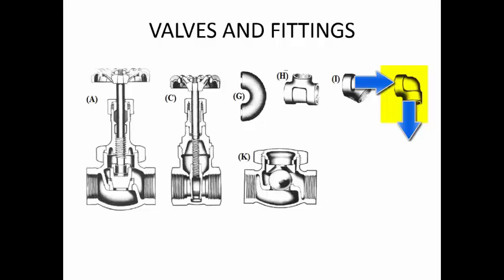Now you have to remember that whenever you are making the piping arrangement of a hydraulic system or any system, you do not get any angle you want, it is not available. So these fittings are available for standard angles. Now if you want some special connections, then it may not be possible using the tube or pipe. In that case, you have to go for a hose. So if you have some abnormal angles, say 120 degrees, where two pipes are coming and you want to join them, then you may not have any fitting. So for the two piping elements, you have to make some thread arrangement so that you can use a flexible coupling or a hose, and you can make the connection.